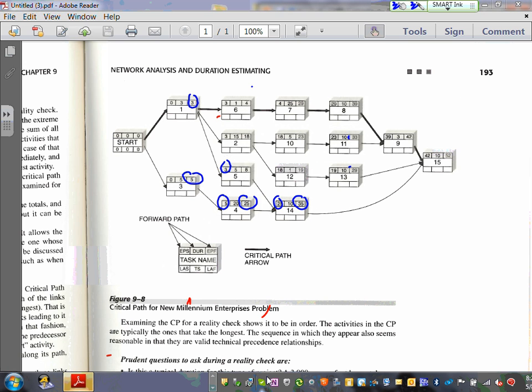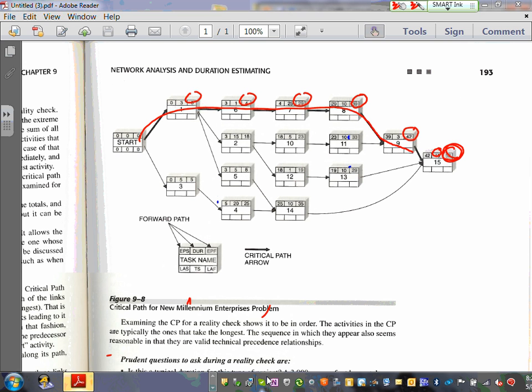So if I have 2 activities, power and lighting, you take 20 weeks, you take 2 weeks, and you give it to me, right? You take 2 weeks, you take 1 week. My start had to take 2 weeks, not 1 week. This is what you're looking at. And ultimately, the critical path, you're looking at it right in here. Look at the 29 here, 42, and here's the 10, and here's what it adds to the end of the project. You see the end of the duration for each activity. This is my critical path, going from here all the way to here.